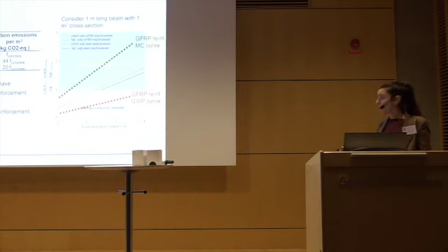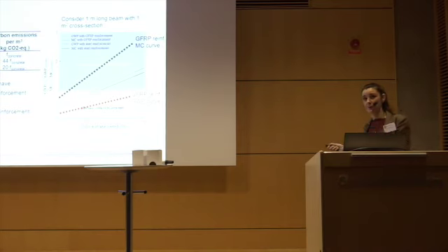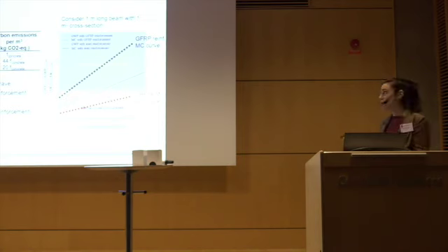But when I look at cost, same material, the thing changes, because if I am above, what is this, like 1.3, 1.4% content, then it is always that the cost of reinforcement is higher than the cost of concrete. So if you want to reduce the concrete, you should reduce the reinforcement amount.